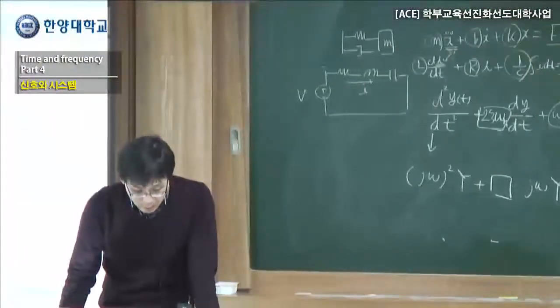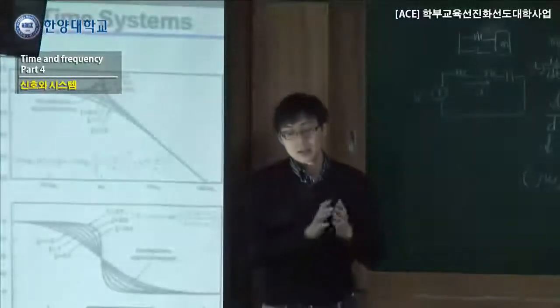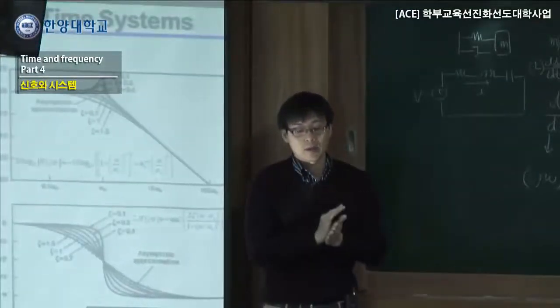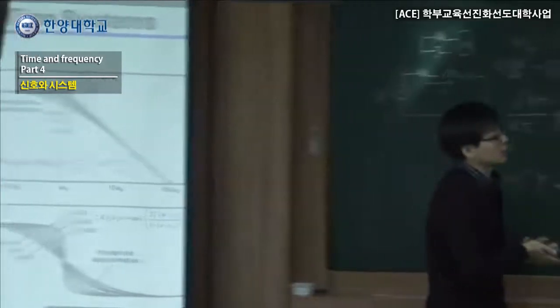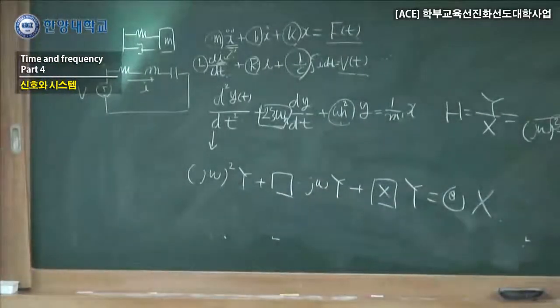When you plot it, as I mentioned, you have to plot in the frequency domain and in the time domain to see how things are different. If you plot this Bode plot, using the same method, when omega is very small, it will be close to 0, and then it falls off. Remember, this is not 20 dB per decade, it's 40 dB per decade because it's a second order system.